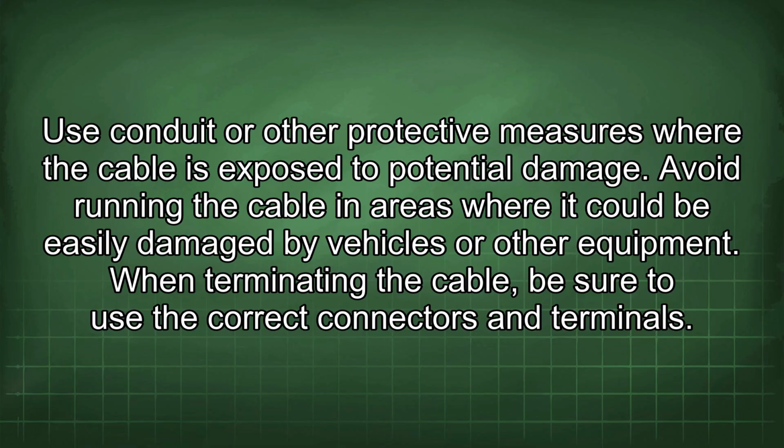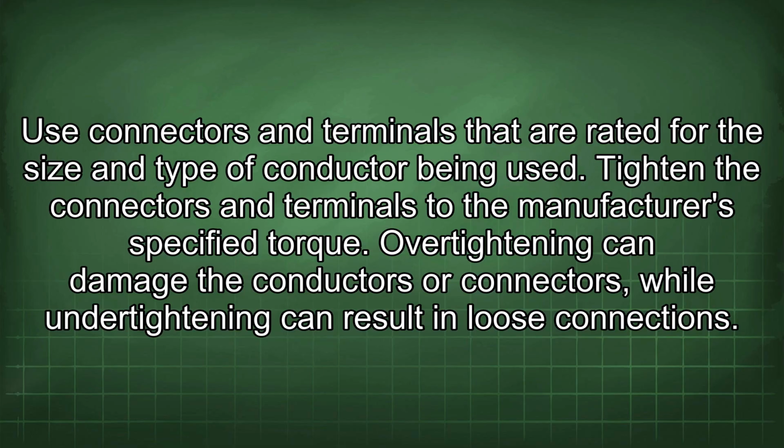When terminating the cable, be sure to use the correct connectors and terminals. Use connectors and terminals that are rated for the size and type of conductor being used. Tighten the connectors and terminals to the manufacturer-specified torque. Over-tightening can damage the conductors or connectors, while under-tightening can result in loose connections.